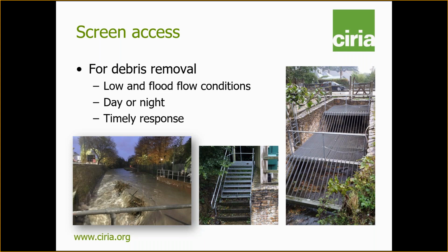The manual brings together guidance on screen design, and some good practice design features include vehicle access, parking, storage for materials, and a clear route to the screen that's free from trip hazards or obstacles. The preference is for steps or a ramp to each level of the screen and the watercourse, and avoiding using ladders unless space is very restricted. We should also look to provide fencing or handrails to reduce the risk of falling into the channel, with gates and removable handrails to allow access to clean different areas of the screen. And we should also provide access to the culvert for periodic inspection via an access hatch in the working platform.